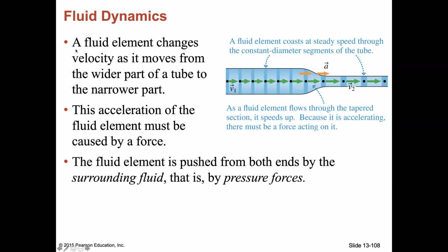Okay, so a fluid element changes velocity as it moves from the wider part of a tube to the narrower part. This acceleration of the fluid element must be caused by a force, because only net force can result in acceleration. And this fluid element is pushed from both ends by the surrounding fluid, which is pressure forces.